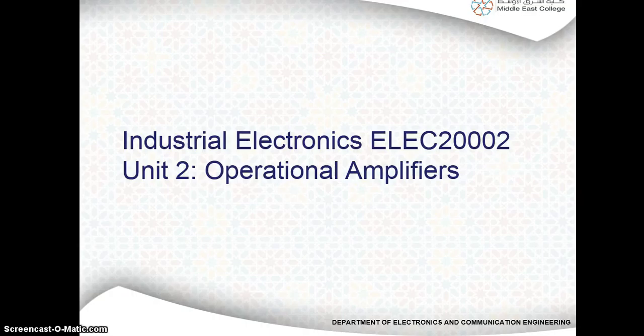The operational amplifier is a device that can be used to amplify DC as well as AC input signals and was originally designed for performing mathematical operations such as addition, subtraction, multiplication and integration. With the addition of suitable external feedback elements, the modern day op-amp can be used for a variety of applications such as AC and DC signal amplification, active filters, oscillators, comparators, regulators and others.